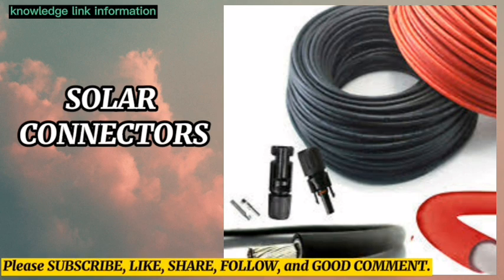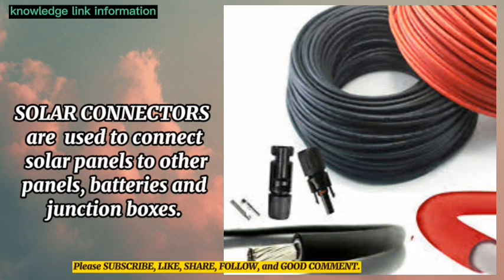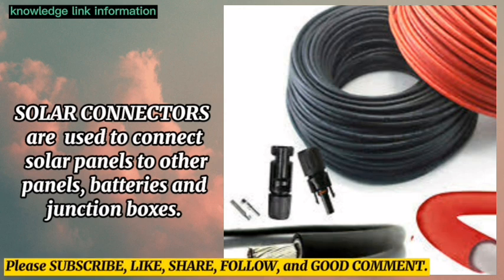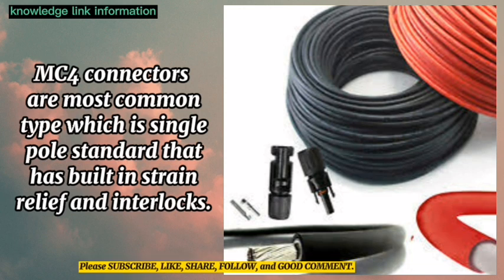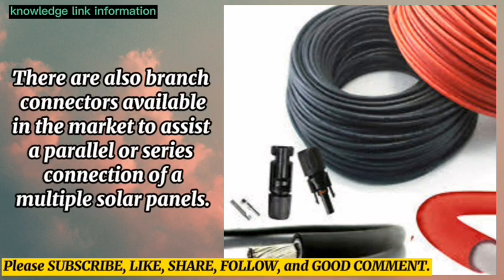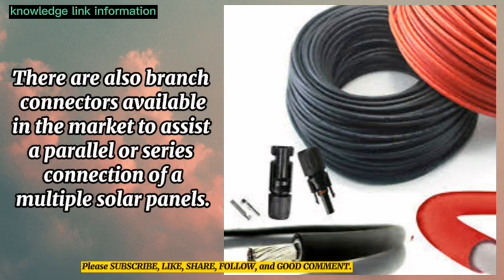Solar connectors. Solar connectors are used to connect solar panels to other panels, batteries, and junction boxes. MC4 connectors are the most common type, which is a single pole standard that has built-in strain relief and interlocks. There are also branch connectors available in the market to assist a parallel or series connection of multiple solar panels.